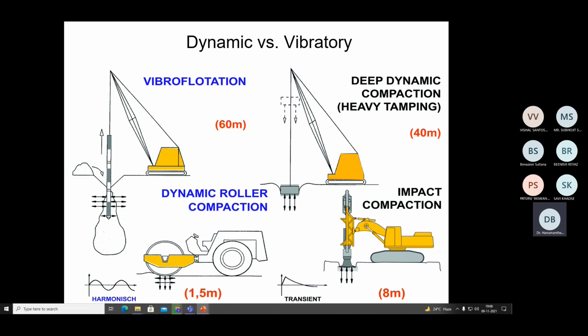However, especially in the lateral direction, as these arrows are showing, this excites the particles, especially in the lateral direction. So whenever there is an excitation energy in the lateral direction, the particles get rearranged and thereby they will get densified. So this is the fundamental principle of vibro flotation. But here we use something called a vibro probe, which will be inserted into the ground.